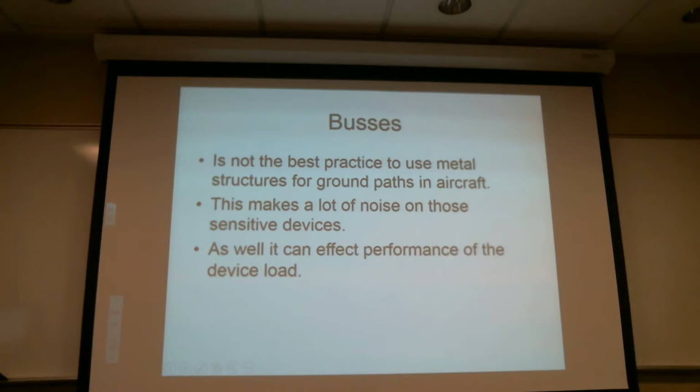Customer complains, I got in, started it, and it was really, really weak, and the speedometer blew a puff of smoke out and then stopped working. Well, in that particular model vehicle, the entire suspension was rubber mounted. The engine was rubber mounted. There was a ground strap. When the ground strap broke, the only possible connection between the battery connected to the chassis and the entire drivetrain was the speedometer cable and the two parking brake cables. It would melt both parking brake cables and lock them solid, which made it a real bear for the tow truck if the brake was on. They'd have to just brute drag the car up onto the truck. And of course that little coil spring in the speedometer, when it saw 300 amps, poof, hence a little bit of smoke coming out.